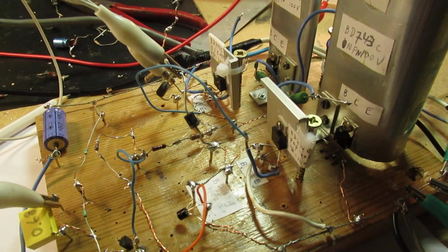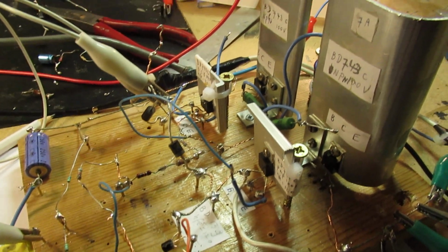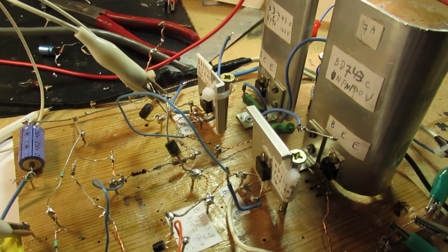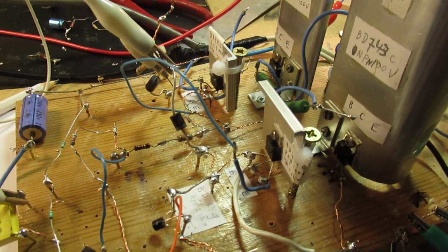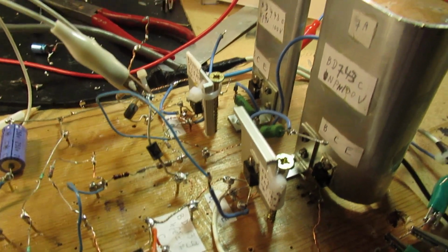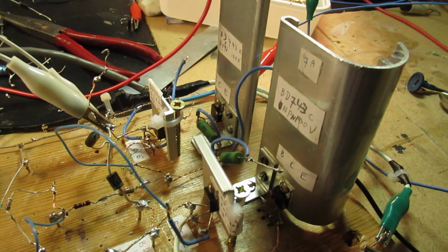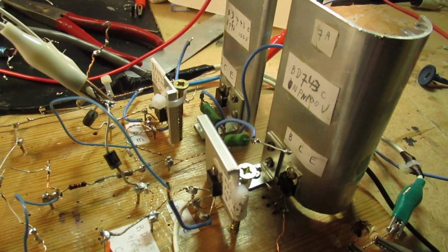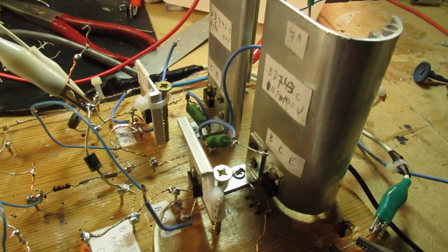And the quiescent current is always very important. When such an amplifier takes a quite high quiescent current, there is no crossover distortion. But when the quiescent current of such an amplifier is pinched off, and I will tell more about it, you see crossover distortion.